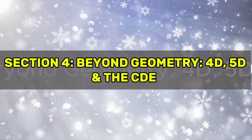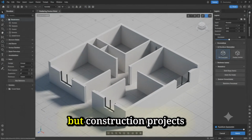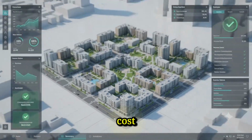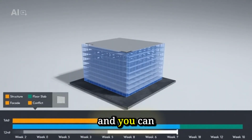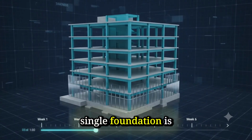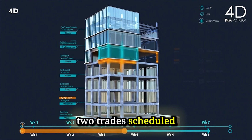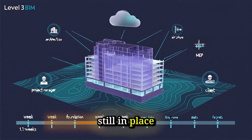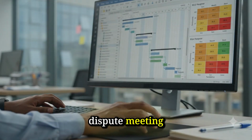Section 4. BIM dimensions: 4D, 5D and the CDE. The BIM model is three-dimensional by default, but construction projects exist in more than 3 dimensions. They exist in time and in cost. 4D BIM adds time. Link the model to the construction program, the Gantt chart, and you can simulate the build sequence visually. Watch the building go up week by week before a single foundation is poured. More importantly, identify program conflicts. Two trades scheduled in the same space at the same time. A crane lift that cannot happen because scaffolding is still in place. In 4D BIM, these are discovered in the model, not on site, not during a dispute meeting.